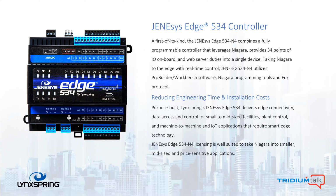As well, it has 2 Ethernet ports, on which we support BACnet IP and MSTP TCP, or Modbus TCP, sorry, and other IP related networks, including Fox. On the very top, we also have a proprietary network similar to what Conservit was showing with their RS-485. It supports our Onyx devices.